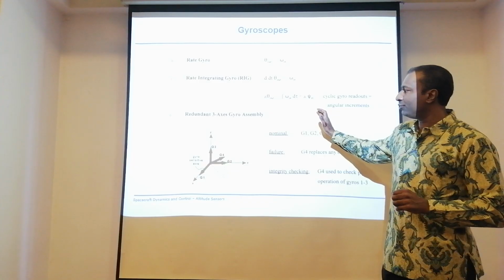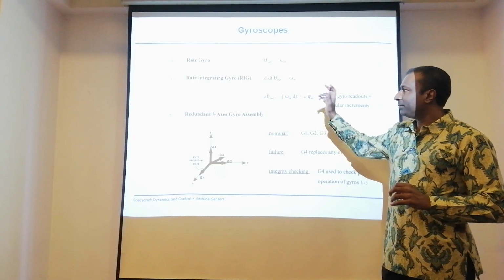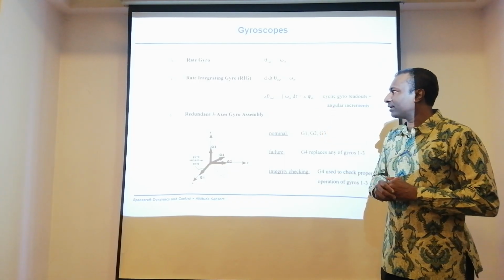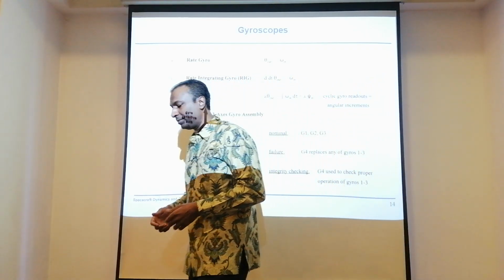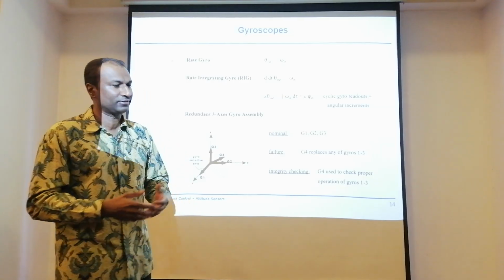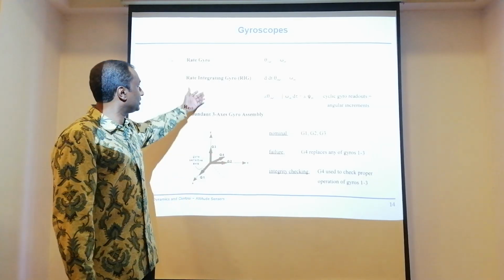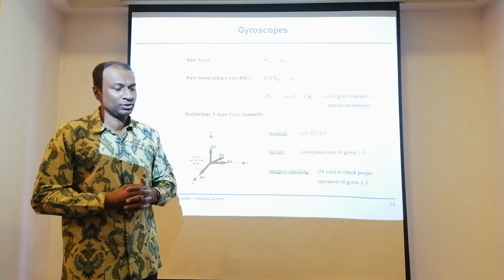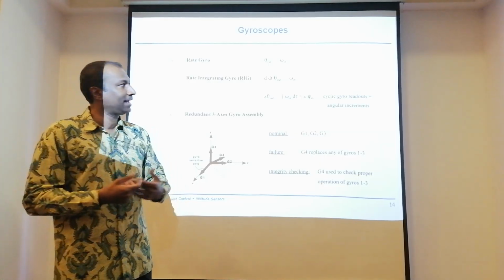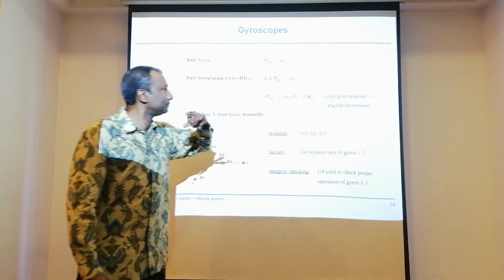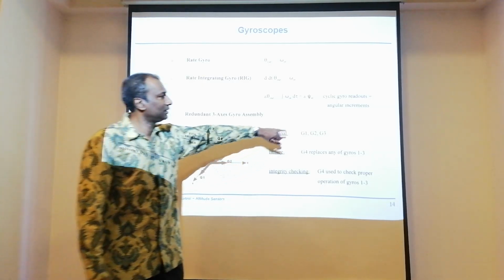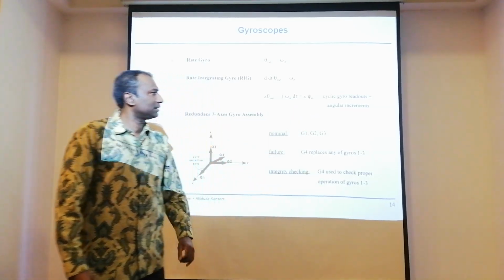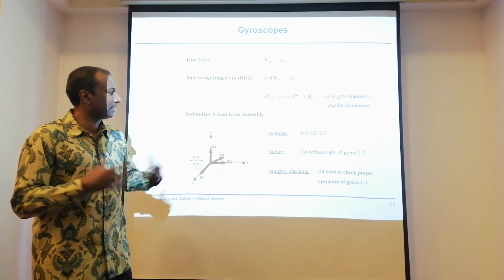Before we go into the fiber optic gyro, with mechanical gyros, when we run the gyro, the output will be angular velocity, but there is also something called an integrating gyro. The integrating gyro gives you the exact attitude. So you integrate that angular velocity, and the readout would be the actual increment of the angle.